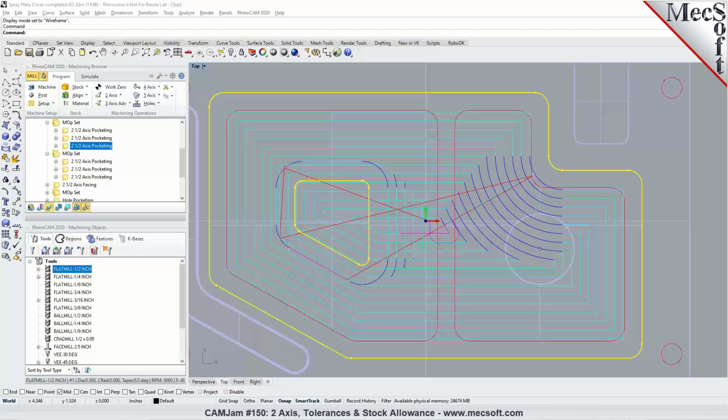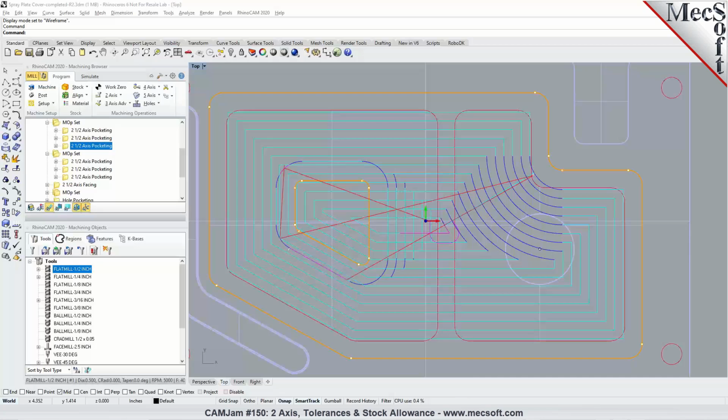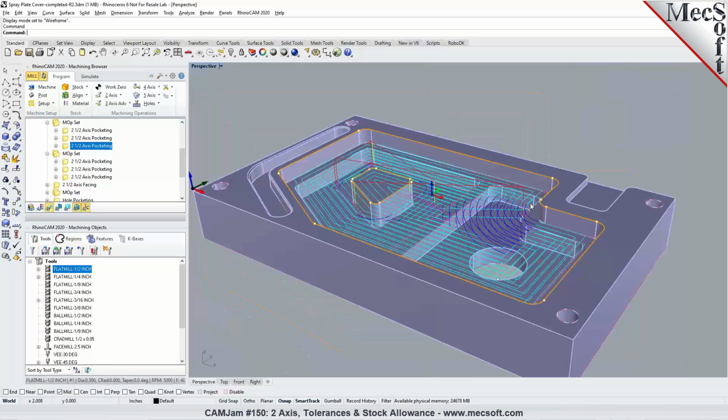Sure. So if you're using a very tight tolerance, one of the things you'll notice is you'll have more go-to motions. If the toolpath is being output as linear motions, you'd end up with more point-to-point moves. So it could be possible on some machines or controllers that the control may not have enough look ahead, and you might see the machine cause stuttering or slow things down.